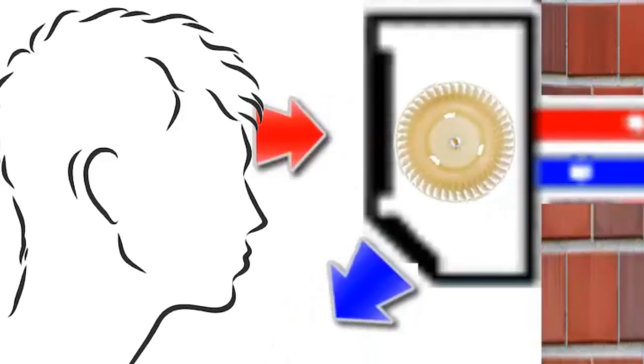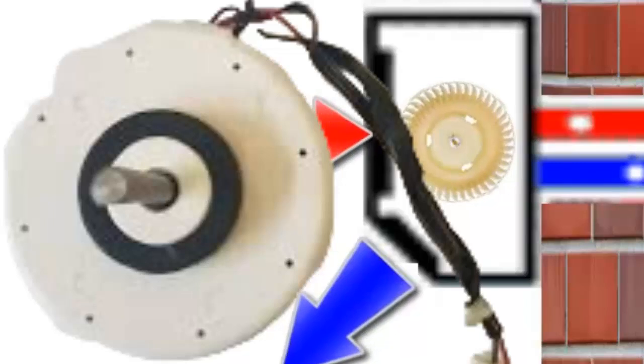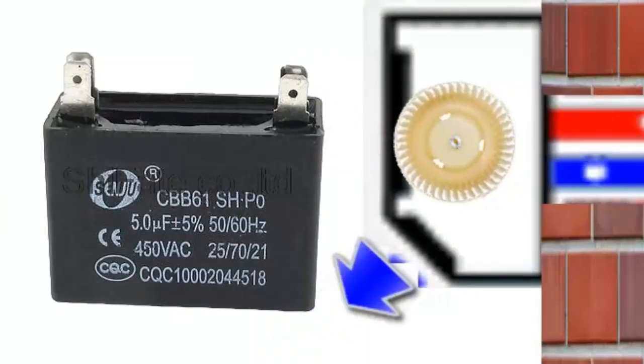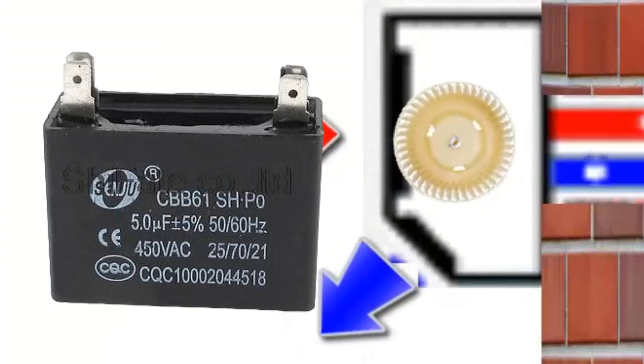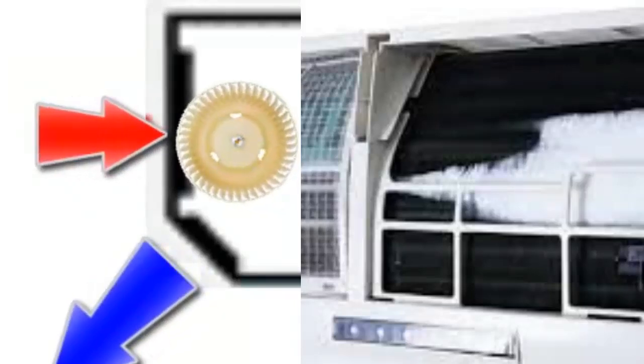2. Observe if the fan or blower of the indoor unit rotates at the correct speed. A failure in the capacitor, worn-out bearings, or incorrect voltage can affect its operation. Slow blowers can have symptoms similar to the lack of refrigerant gas.